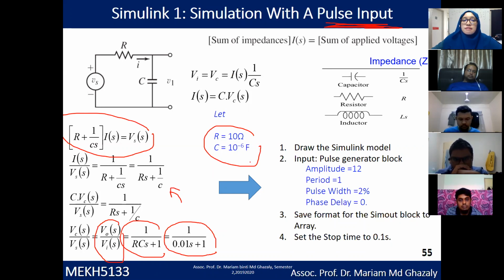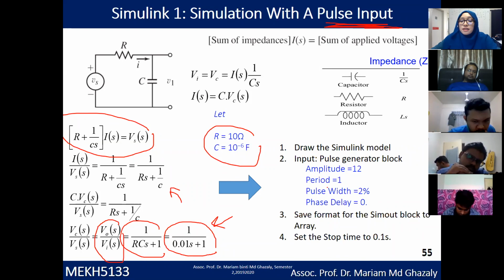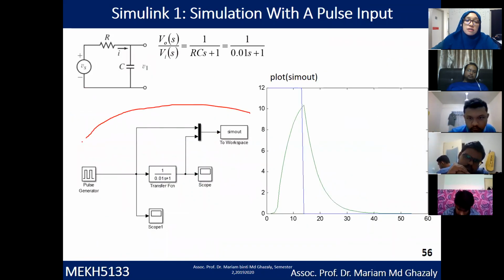So first, this is the circuit, and you already found out the transfer function. So plot this transfer function when we have a pulse input. First of all, draw the Simulink model, which is what you're going to draw out.